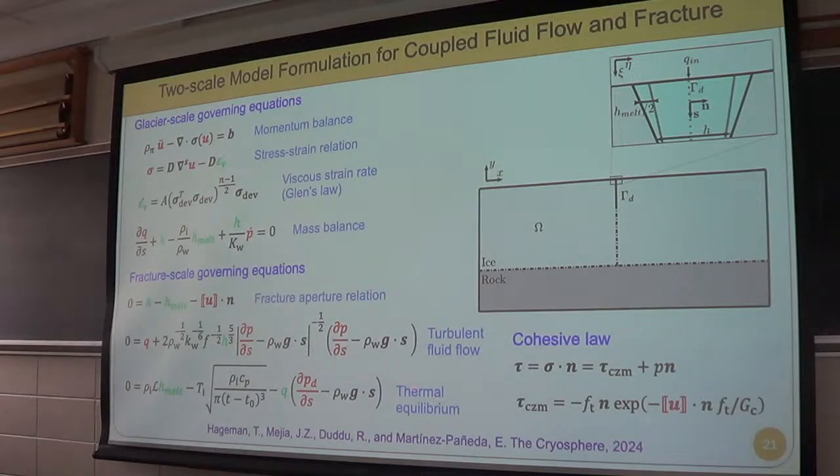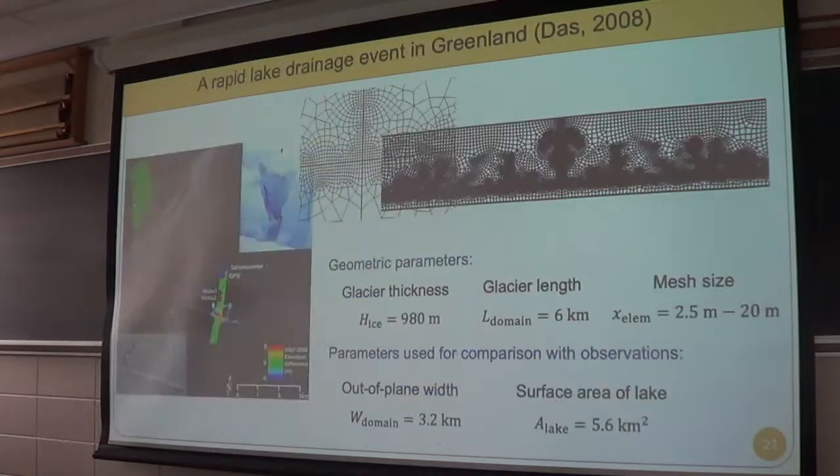And then we have fracture using this cohesive law, where what it's telling is that the opening displacement is related to the stress in the surrounding material. Right? So detailed model, sorry that took so long, and then we have to mesh it with the finite element. And so anywhere we have the main fracture, we have to mesh it appropriately. And then this is the basal interface where we also have fracture elements, interface elements. So there also it's meshed. And then this adaptive refinement saves us some computation cost.